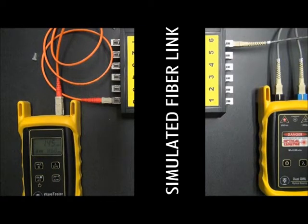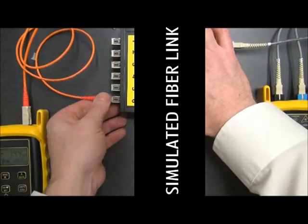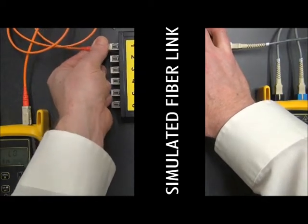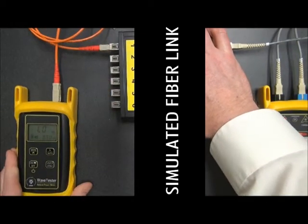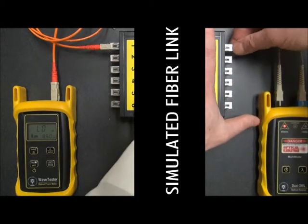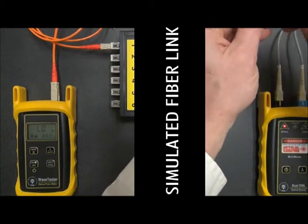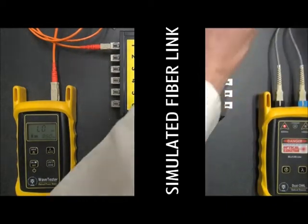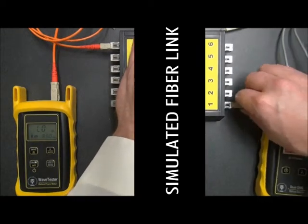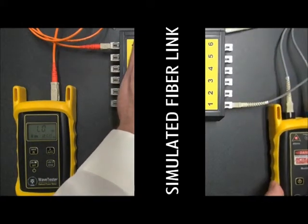So now that we've stored all our readings at 850, we'll switch over to the 1300 wavelength. But first, we need to plug into port number 1 again, because remember, we want to keep our numbers in sequence. So we're going to test in the same order. That way, on the software, the 850 reading for fiber number 1 will stay with the 1300 reading for fiber number 1.